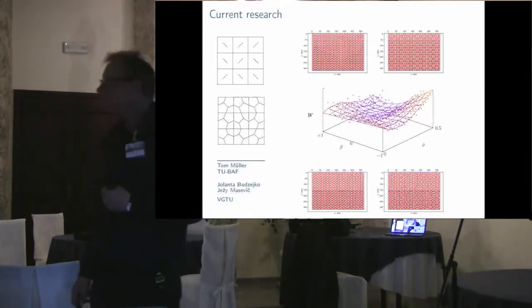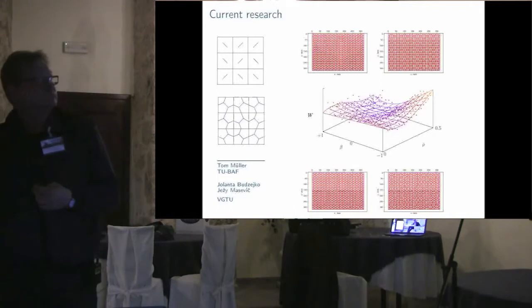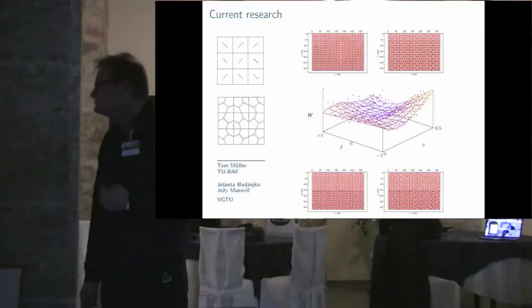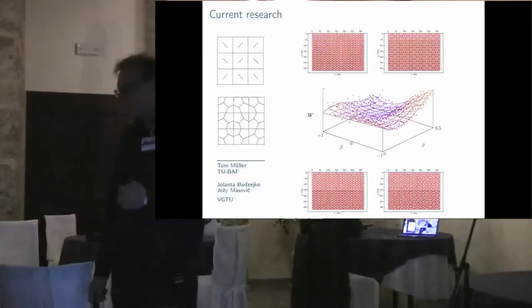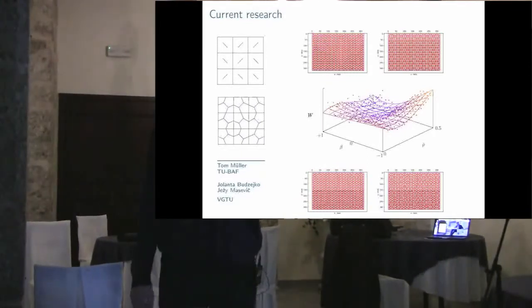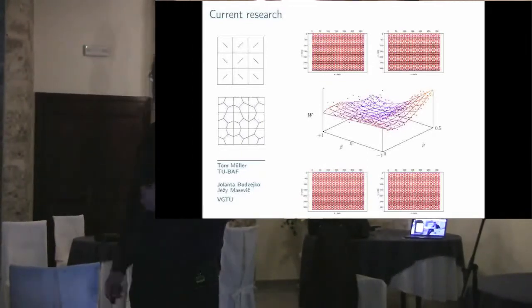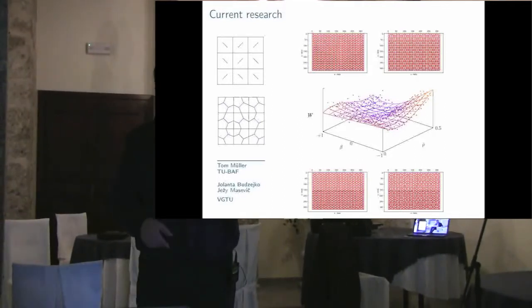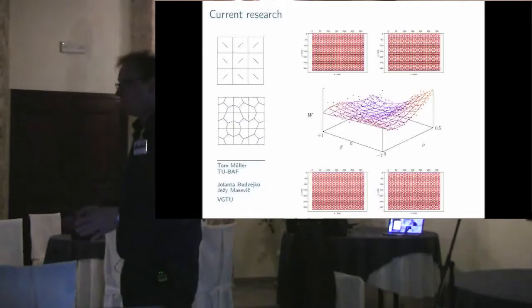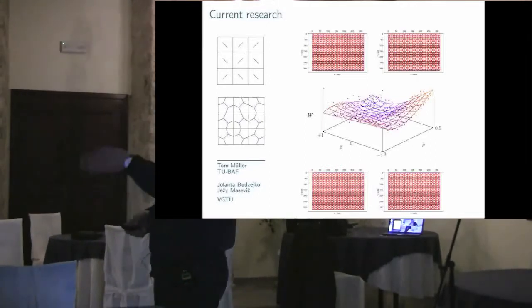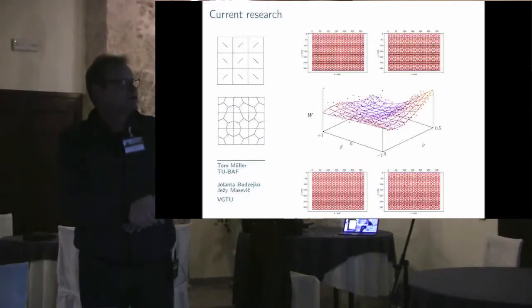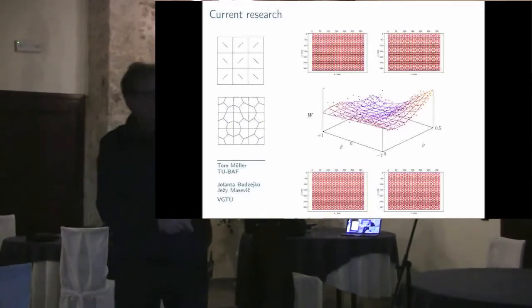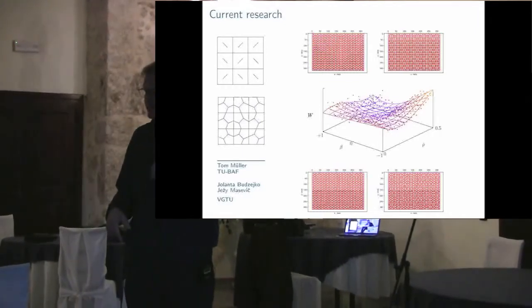So did you consider the RVE size of this case, by changing it? For the truss structures we did. For the beam structures here, not in a systematic way. So we try 10 by 10, 15 by 15, and then we check how the results change, especially for the completely disordered structure.